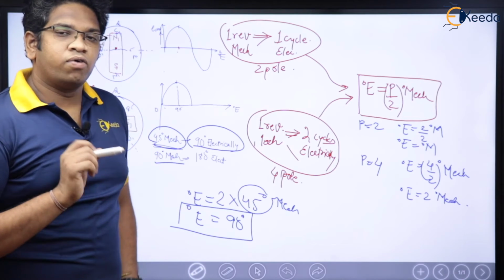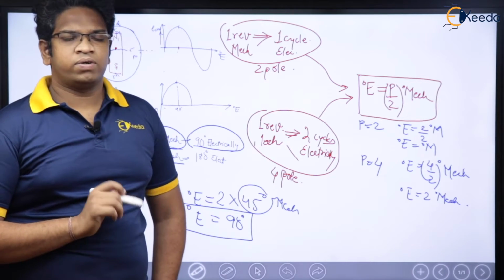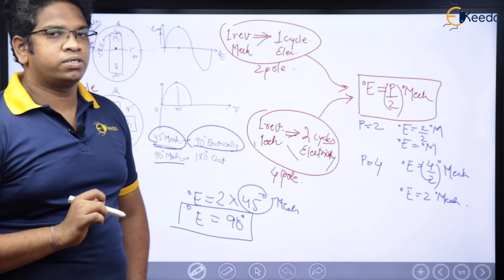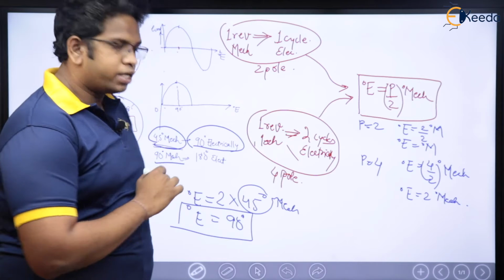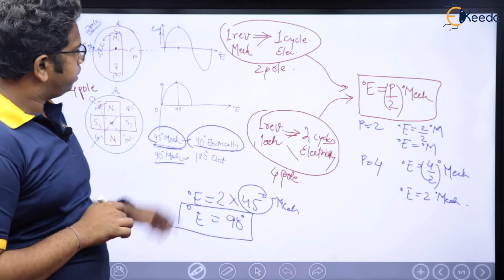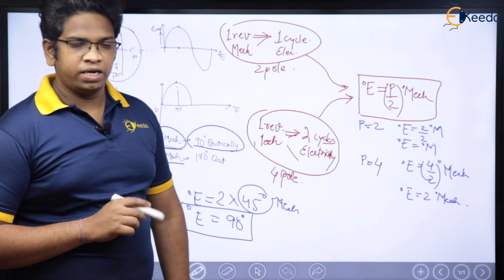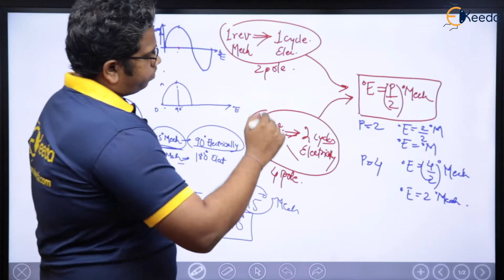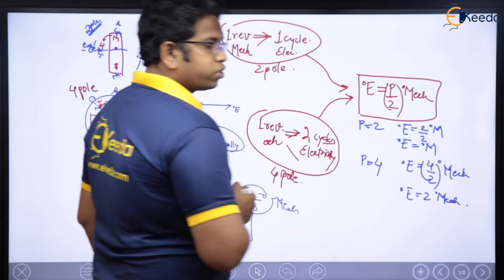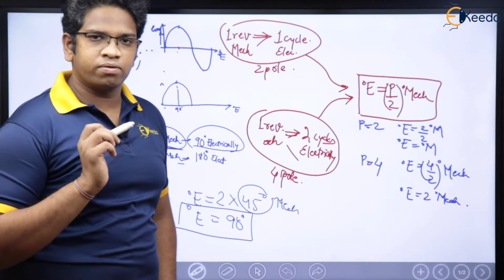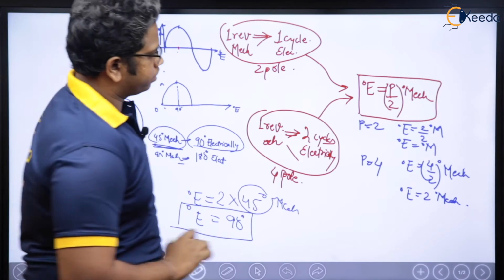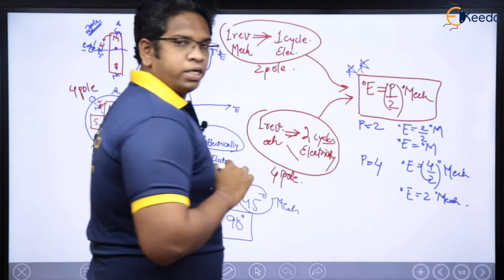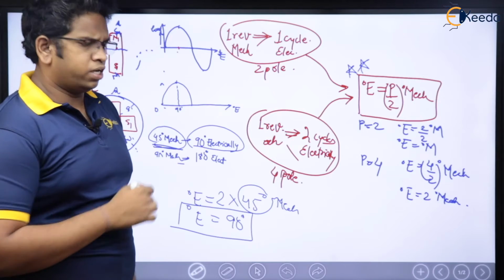So from now, whatever angles we have, whether it is slot angle or any angle, those angles have to be what? Always electrical angles only. Why? Because we are interested in induced EMF. Anyways, let us try to understand how to find slot angle now. By the way, see here, this formula which is there, degree electrical is equal to P by 2 times degree mechanical. This formula is very, very important. Let us see how it is important. This formula is going to be very, very important in terms of exams as well and for understanding purpose also.